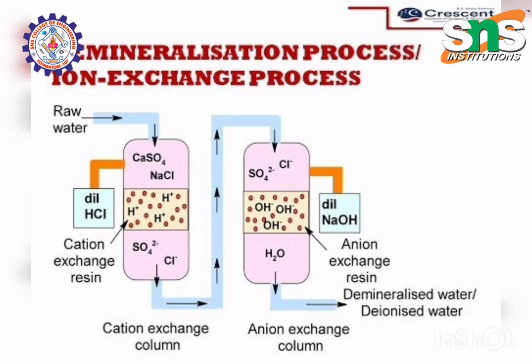The advantages of the ion exchange process are that both acidic and alkaline water can be treated, and the water produced from this process has very low hardness. It is nearly reduced to 2 ppm of hardness.